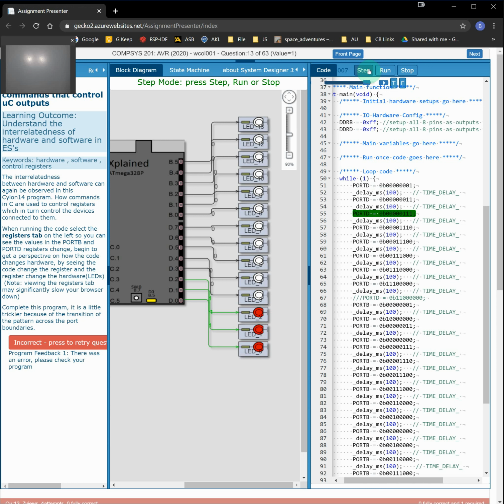And what happens in the next line of code is that we want to turn on this LED, and very commonly students will write code that turns on this LED but forgets to turn off this one, and so you'll have 4 LEDs on instead of 3, and that's because there's a subtle assumption that the microcontroller will read your mind. We're all inclined to do this a little bit, so we need to be really explicit. Computers are incredibly stupid. They will do only what they are told to do.